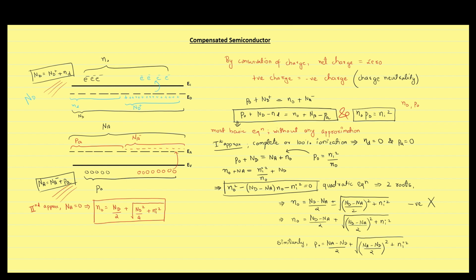This is the exact formula for free electron concentration when we are having a normal n-type semiconductor which is not having acceptor impurity and the temperature is also sufficiently high such that complete annihilation has taken place. Now we will put the third approximation, which is Nd is significantly greater than Ni, meaning that Ni square can be neglected in the under root expression, giving us free electron concentration to be approximately equal to doping concentration.